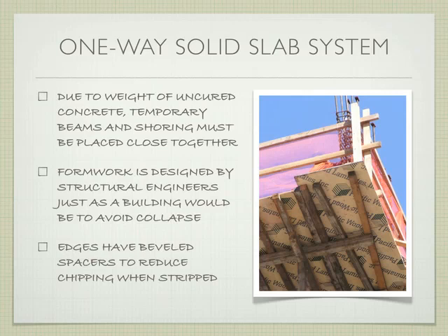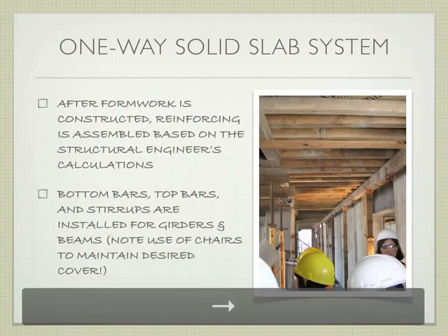So it's very rare when we have a nice sharp corner. Generally on the bottom of a beam, if you go into a parking garage, look up and you'll see this, generally every beam or girder has a chipped corner, or a chamfered corner because it's easier to remove the formwork. You don't have an edge that accidentally gets chipped and then looks bad.